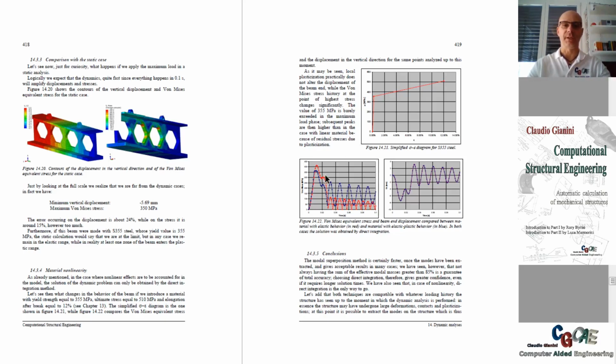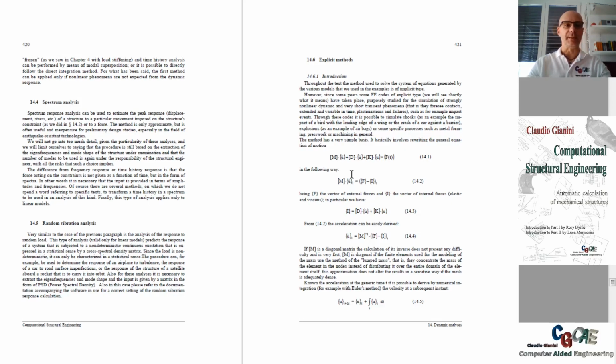And we show here what is happening when we enter into plasticity by having this bilinear material behavior. In terms of displacement, there is no big difference, but in terms of stress, there is quite a lot, especially in the rundown, so to say, where clearly the stresses are different because we have some residual stresses coming from the first yielding of the material.